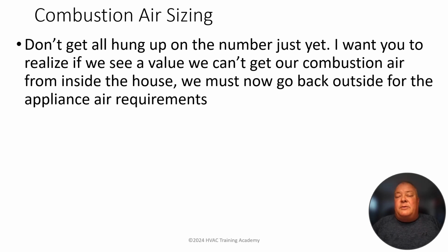Don't get hung up on the number. I want you to realize when you see the value, we can't get our combustion air from inside the house, so now we have to go back outside for appliance air requirements. And I'll tell you the reason why I tell you don't get held up in the number. A lot of technicians, as soon as they see that number, think that if I cut a hole in the wall that's 18 inches square, then I've satisfied the requirements to get the air to my appliances.